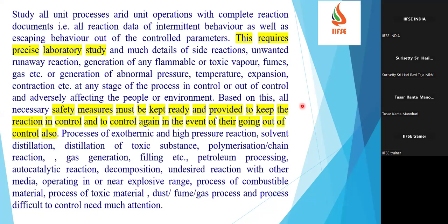So we have to understand all the aspects of the reaction process so that we can lead the process in a safer manner. Based on understanding all these issues, like how side reactions happen, or whether there is any chance of an unwanted runaway reaction, if an unwanted reaction happens, how can I control it? And in case of any abnormal pressure, what is the limit of that pressure? And also temperature, any expansion, contraction in the vessel, all these things have to be considered.